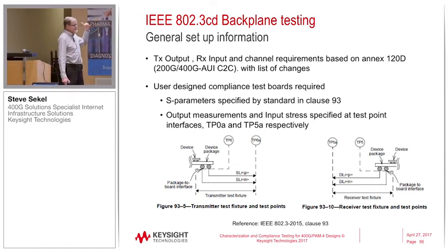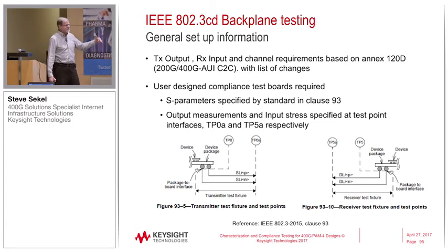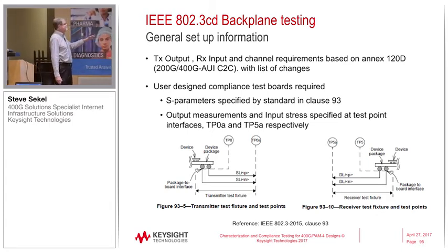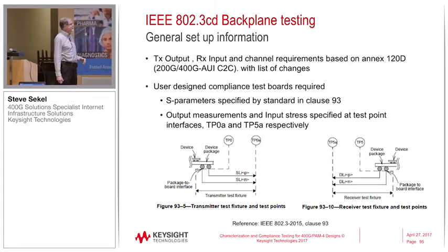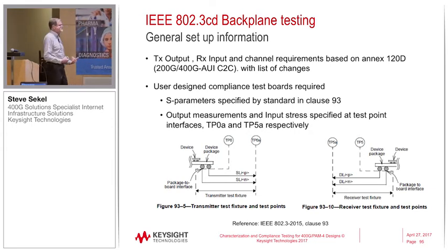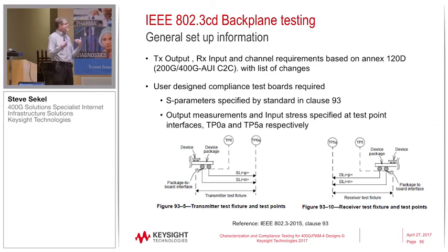120D is the chip-to-chip standard in 802.3bs, and it's probably going to apply to backplanes because that cross-references a 100G backplane. So they're starting with a backplane, they're going to a medium reach channel, and now we're wrapping around to a faster backplane spec. So, list of changes.